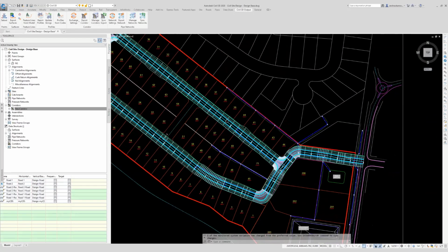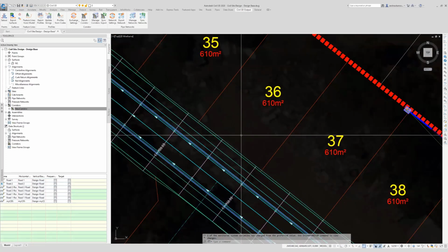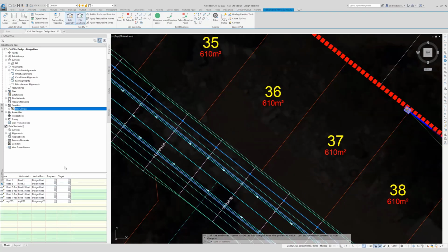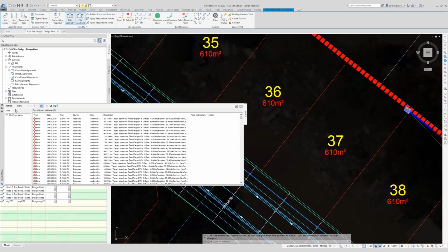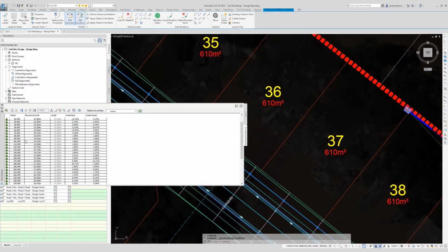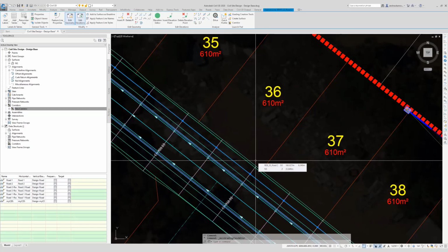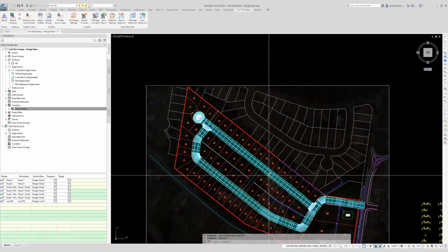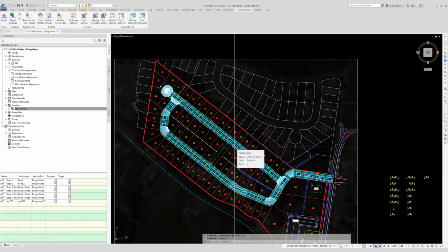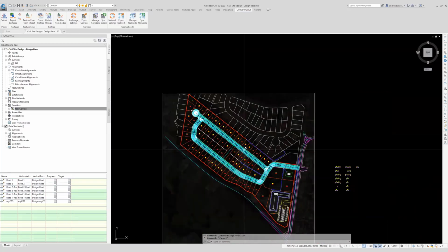And when I go and click on Export, I have a whole bunch of feature lines that have been created. All right, so I can click on the feature line. I can open up the elevation editor. Okay, and we've just populated that with all the elevations. So the beauty of having a feature line, you can start grading using the Civil 3D grading tools. You could build some surfaces by just taking certain feature lines. We will do more on that command later. So this is sort of version 1 of it, but we'll do a lot more on it.